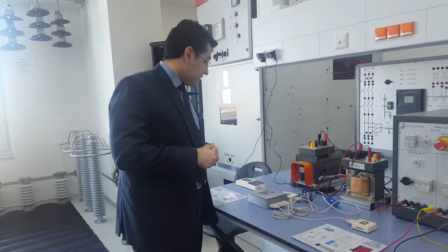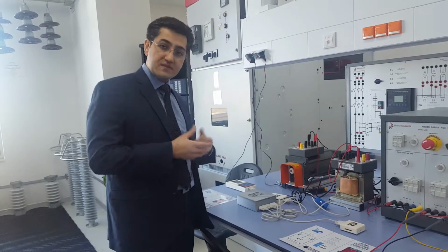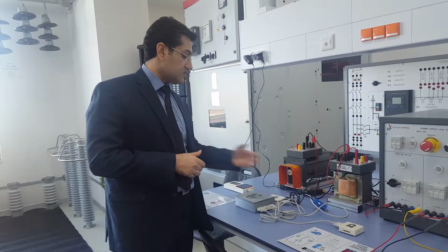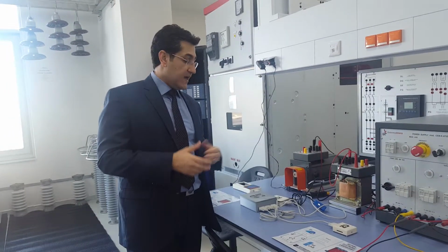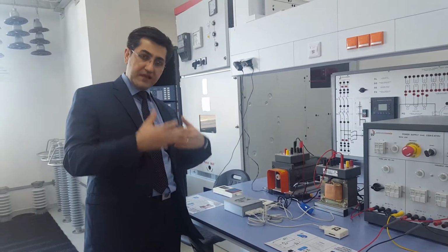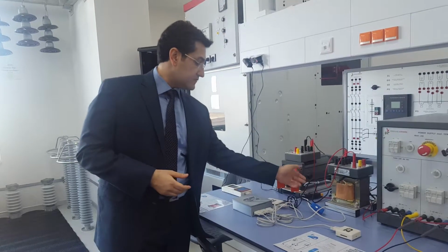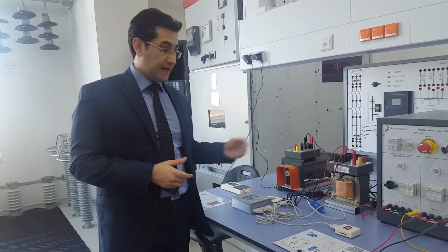The analysis, the demonstration, everything is going to be the same. The cloud is working for all the ranges. This is the only thing which you need to change: you need to change the CT. And of course, if you are using the LV system, you're going to take a sample from the LV system, not from the high voltage. For any LV system, you can simply use a 5 ampere or maybe 100 ampere clamping CT.